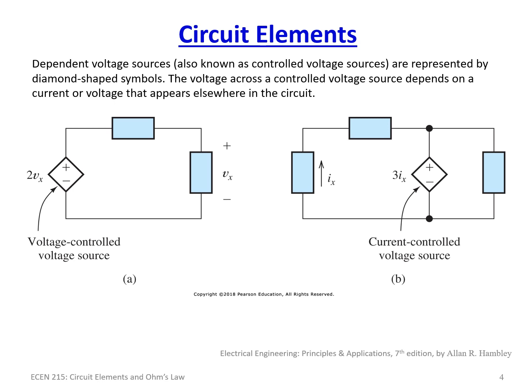These type of circuit elements are dependent sources, meaning that they depend upon other voltages or currents to do its element. So in this case, this power supply here is a voltage controlled voltage source, and it's going to generate a voltage that is 2 times Vx. And usually you will see in the schematic of reference where Vx is defined must be set. So in this case, Vx is considered the voltage across this element here. So the voltage here is going to be 2 Vx, and you would have to figure out what Vx is, and you would insert that value into this equation.